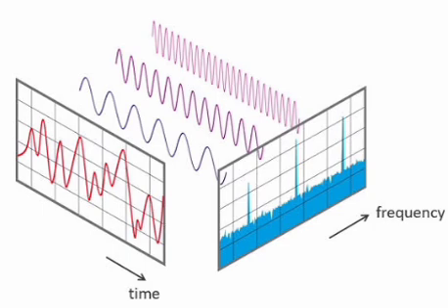Phase delay is the delay offered to the phase of the input consisting of a single frequency. Phase delay equals minus phi of omega by omega. Group delay is the delay offered to the phase of an input consisting of multiple frequencies. Group delay equals minus d phi of omega by d omega. For distortionless LTI systems, both group delay and phase delay are constant and are equal.